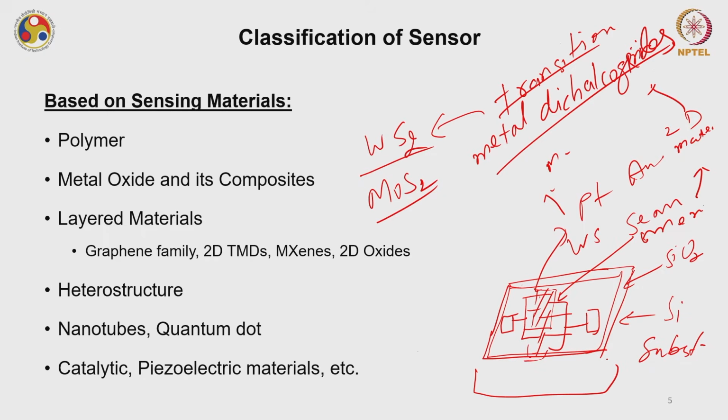If you see the structure of this chemi-resistive device, it has all the components. It has conductors, as I have mentioned that these electrodes are made of platinum or gold. Then I have SiO2 in this picture, which is an insulating oxide, so I have an insulator.